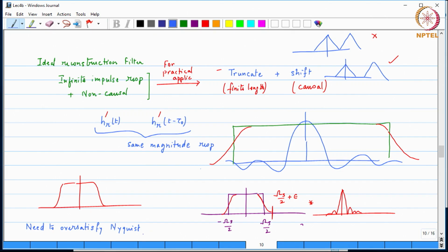That is why we say that we always want to over satisfy the Nyquist criterion. Okay. So, basically choose your sampling frequency to be greater than 2 times omega naught, the band limited signal. Okay. So, again I hope we keep in mind the key elements there.